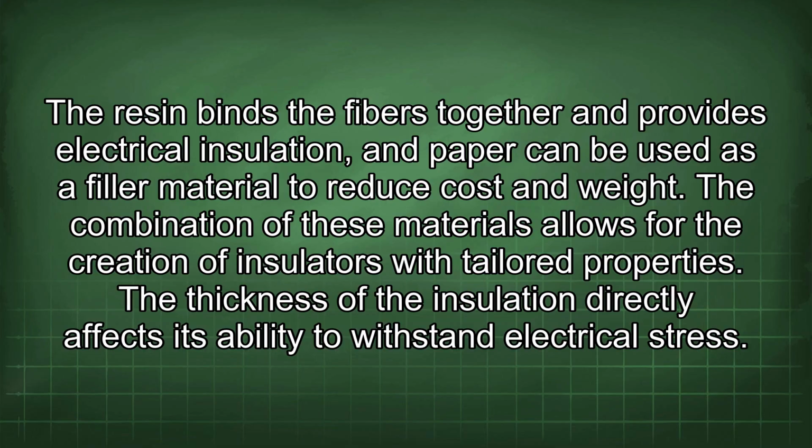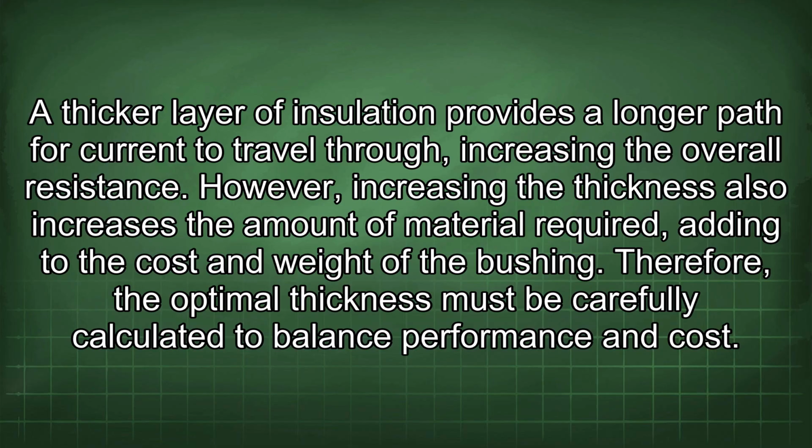The thickness of the insulation directly affects its ability to withstand electrical stress. A thicker layer of insulation provides a longer path for current to travel through, increasing the overall resistance. However, increasing the thickness also increases the amount of material required, adding to the cost and weight of the bushing. Therefore, the optimal thickness must be carefully calculated to balance performance and cost.